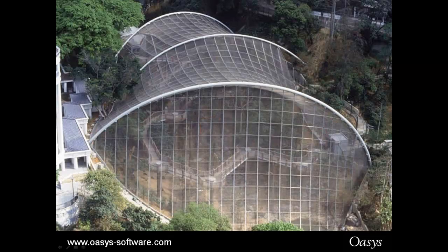Likewise, in compression only structures like this, if you want to achieve that slenderness and so on, then the form is crucial to prevent buckling and moments and so on. And you can use form finding to create balanced structures such as this, where you've got the compression only and tension only elements all together.